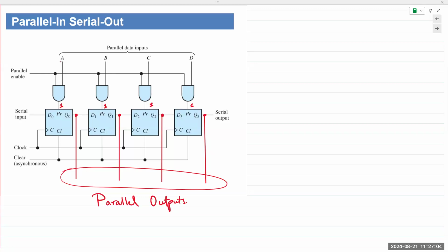Okay. So let's take a look at how this is going to work here. AND gate, multiplication, output goes high only when both inputs are high. It's 0 and 0, 0 and 1, 1 and 0, 1 and 1. So if any one of the inputs to the AND gate is low, meaning it's 0, then the output goes to 0. For the output to be 1, both inputs to the AND gate must be 1.